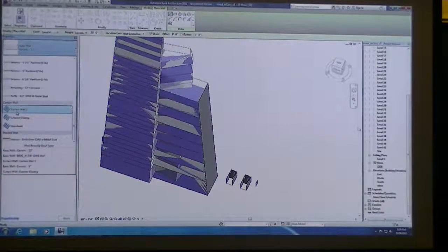usually bigger mullions, so you have like a 2-inch wide mullion by, might be 7 inches deep. A storefront system is usually attached at the jambs and can only go up 15 feet or so. Once you go above a certain height, you have to go to a curtain wall system. A storefront system usually has smaller mullions, so you might have a 2-inch wide mullion, but maybe the depth of the mullion is only 4.5 inches. It can go up to maybe 6 inches, depending on the height.